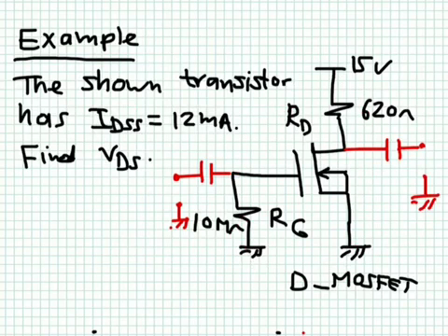But when we start to apply an AC signal, we are actually making all currents and voltages oscillate around the DC value. So we impose on the DC value a small value here, and this creates a tiny swing in the VGS voltage, and this is amplified into a big swing in the drain current, which results in a big swing in the output voltage. So you get an amplified version of your input signal here at the output.